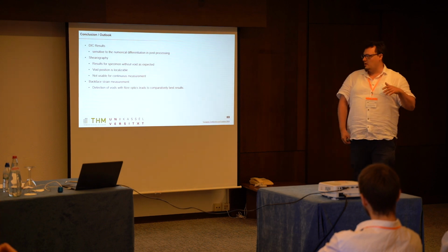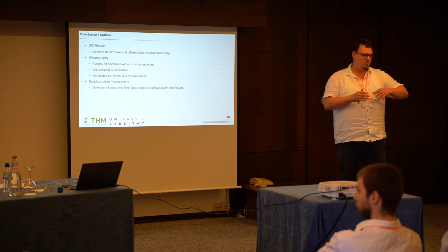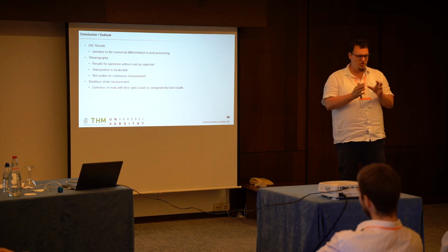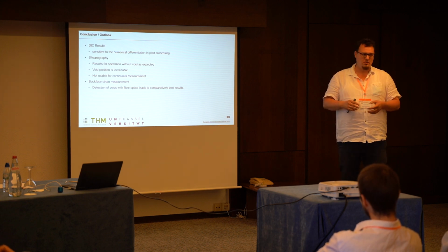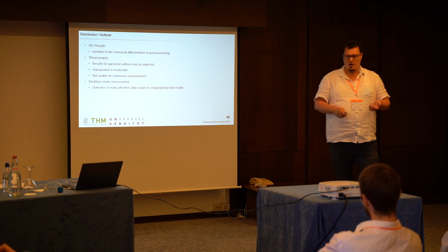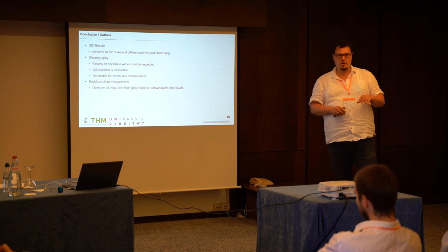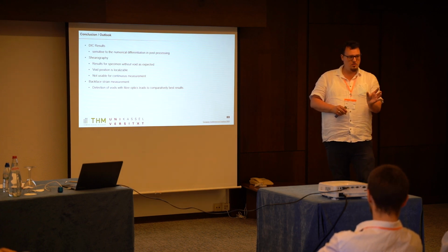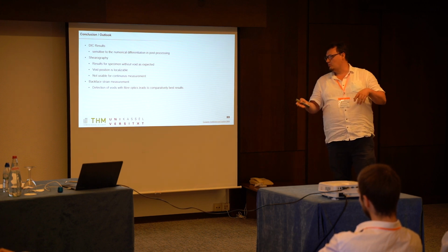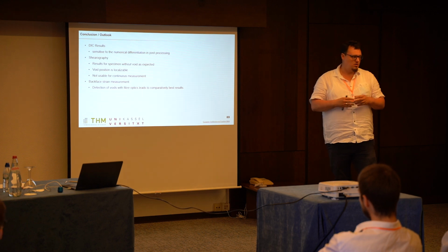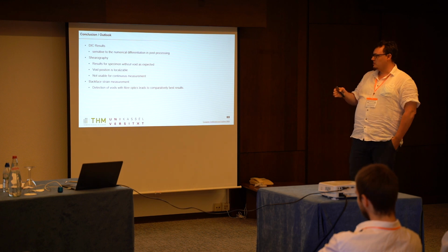For the DSC result, we can locate the void, but we can't measure the size of the void, and it's different because we have large sensitivity to the numerical differentiation. The shearography is quite good to locate the position of the void, but not the size. And the specimen without void shows the values like we expected from the bending, from the deflection curve.